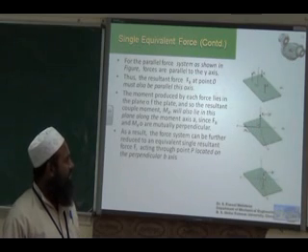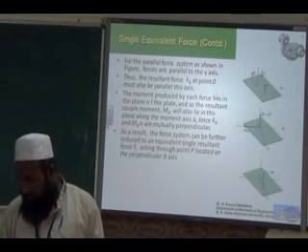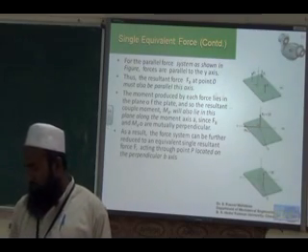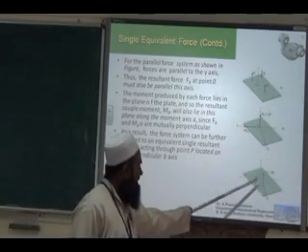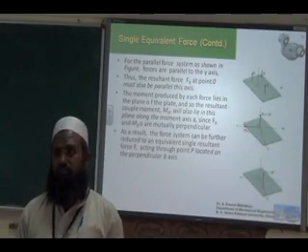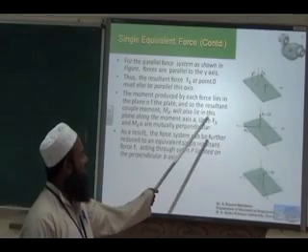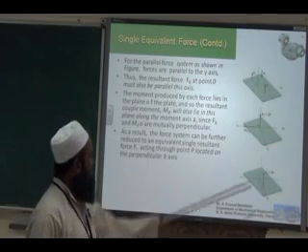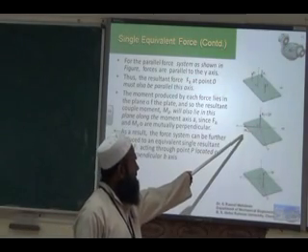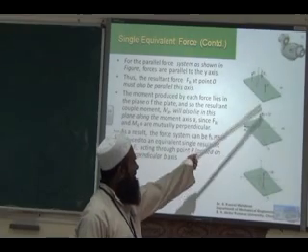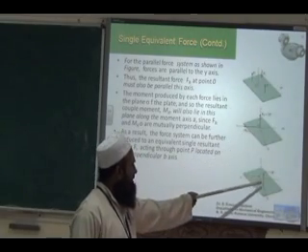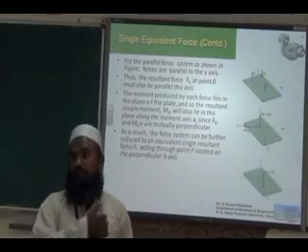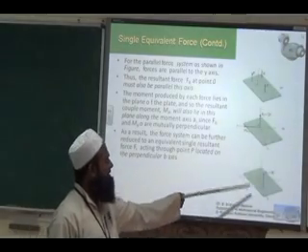So we convert it into a single force system by moving it to distance D. Okay, because the forces are not in the same plane, they are not coplanar, they are parallel. First we find out the resultant force, and also the resultant moment because of each force. Then move the force to a distance D. The D is equivalent to Mr by Fr. But in the axis perpendicular to the two axes.